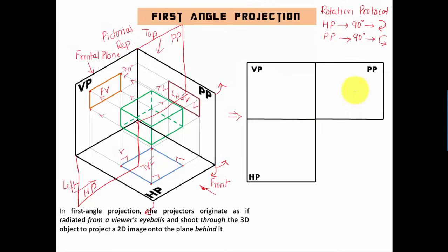So this is going to be your profile plane, okay, and we're going to start off by making this front view initially. You can start off with any view. It is advisable to draw the front view or the top view initially, and then you can get going with the side view. And we're going to know what this distance is. We're going to make a point, and then we're going to go ahead and make this front view, something like this. So this over here represents the front view, and you can see this projector line over here, this line in the downward direction, and this angle initially was 90 degrees.